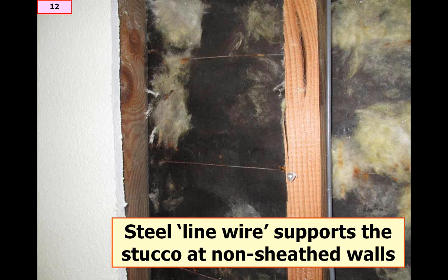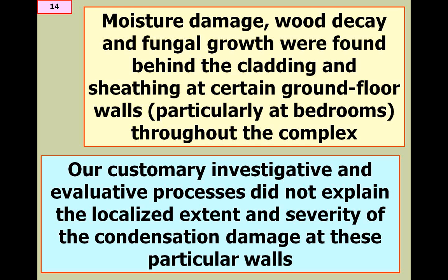So we still approached the investigation in our traditional way, where we start with the assumption that the water is coming from the outside of the building, which makes the most sense because even in drought-stricken California there's still a lot of rainfall, and construction defects and misinstalled flashings can allow water to enter the building. But for this project, we carried out a variety of destructive investigations and moisture testing, and conclusively demonstrated that the conditions you saw in these recent photos did not result from rainwater leakage from the exterior.